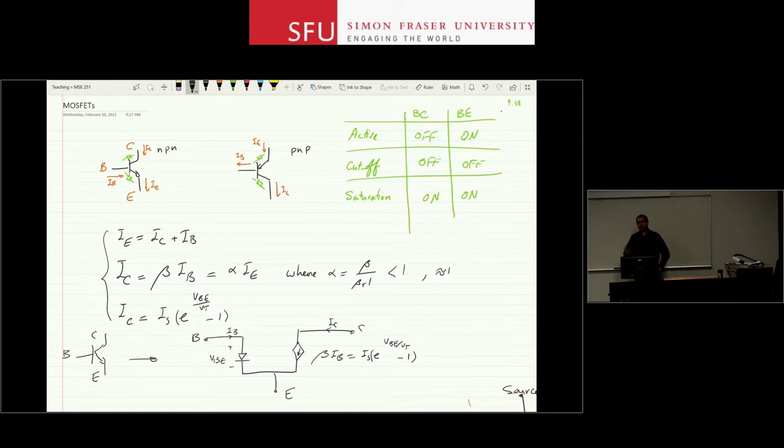If you design an integrated circuit, yes, you most likely have to just go and do the design using MOSFETs. But if you are designing a discrete circuit that you want to make on a PCB, you want to put it on a board, you want to try that at home, there is a very good possibility that it's a BJT. BJT transistors dominate the discrete device market by far, right? So if you want to go and find a small signal MOSFET, your options are actually very, very limited. But for BJTs, you have tons of different varieties that you can choose from.